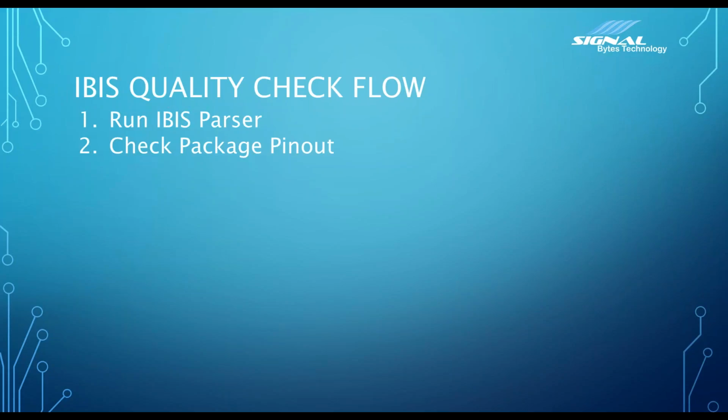Then you should always check your package pinout. If this is a 20-pin device, all 20 pins should be in there, properly defined with the RLC. This is really important for post-layout analysis. If you bring these models into your post-layout board tools and run simulations, lots of times you're going to need to have the full package there. You should also view the IBIS IV and VT data. There's a lot you can learn by looking at the data structures. You can find errors quickly, so it's always good to get an intuitive sense of these curves and how they're working.